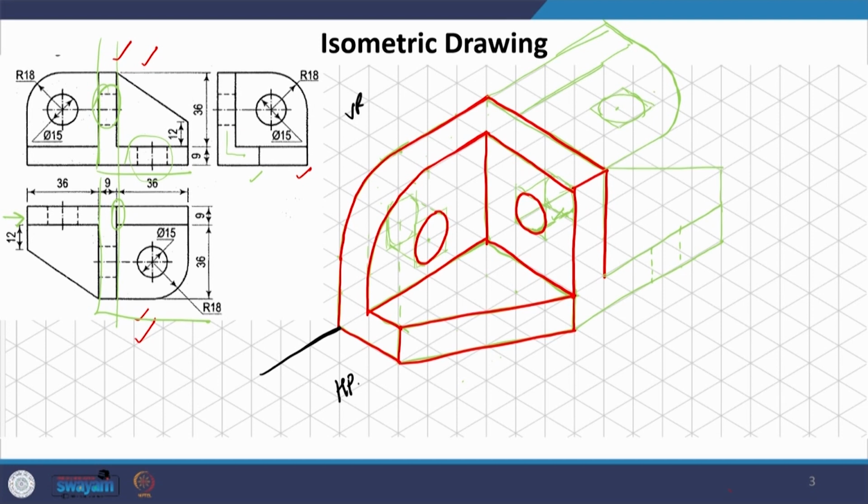Okay. Now, since there is a distinct line, either this is a curved surface or an incline, and very clearly we can see that this is an incline and it is this surface, it is at this level. So, at this level and this level, this is an inclined line, because in the front we can only see one line. So, it is one single incline, which is what we will do, we will just take it back.